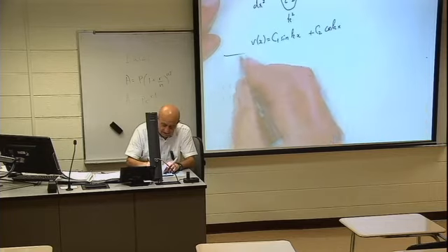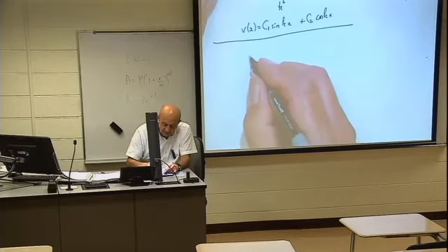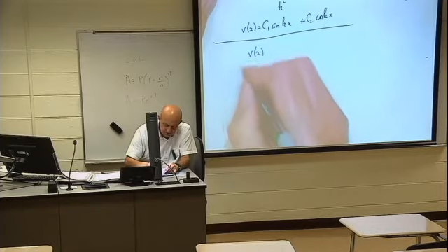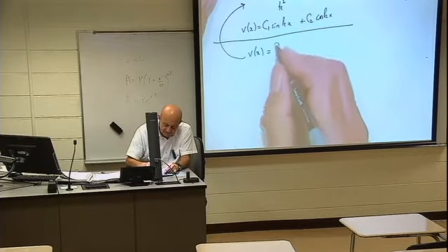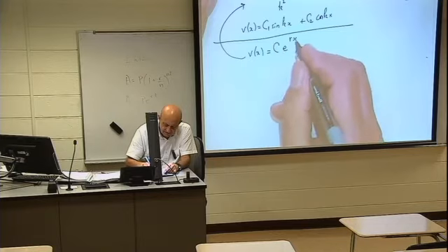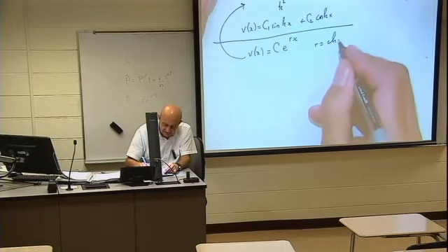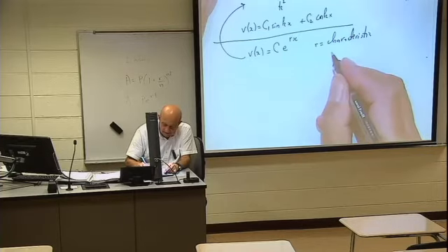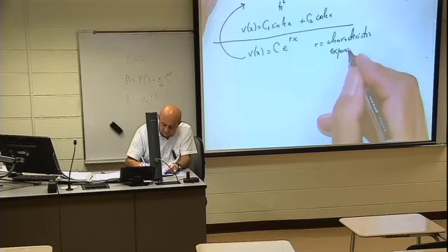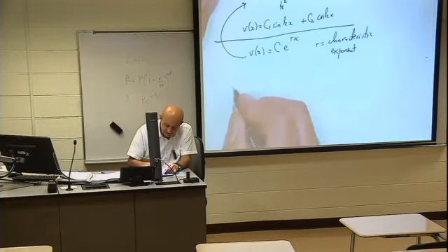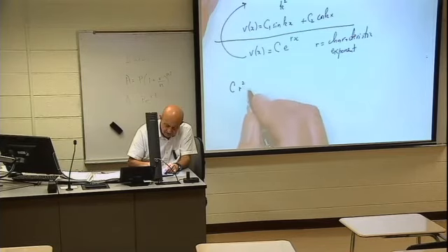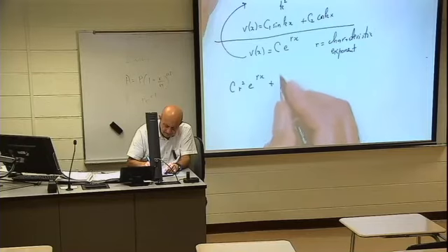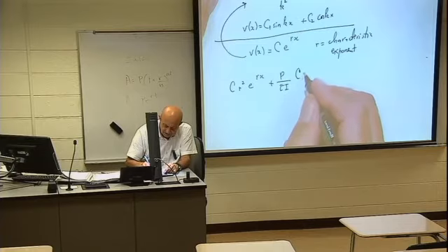But I will derive again. So look, please. V of x, we are looking at c times e in power rx. R is characteristic constant, exponent. I substitute this there, will be c r squared, and then e in power rx, then plus p over EI times c e in power rx.